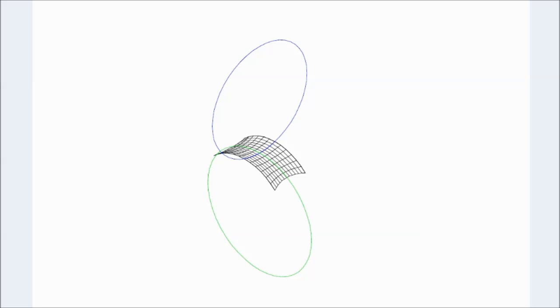The pre-stress value, which is determined by the amount of compensation applied to the fabric at an earlier stage, is the main value that determines how the structure reacts to loads. A high pre-stress results in a stiff structure that will resist applied loads with low deflections, but will need a strong material and supporting structure. A low pre-stress results in a structure that will deflect more with loads, but can be built with a weaker material and supporting structure. The key point is that whenever an external load is applied to a tensile structure, it will increase the fabric stress in one direction and reduce it in the other. Note that fabric stress is always measured in lineal stress, which is pounds per running inch. 2 pounds per inch is a common pre-stress value.